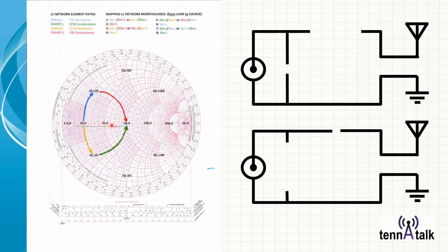So I need to get it over here to 50 ohms, 0 reactance, but I can't get there directly. Now, I could if I had the appropriate UNUN, but most of the time you wouldn't use an UNUN because most of the time you're not perfectly 0 reactance. You've got some reactance, either positive or negative, in the system.